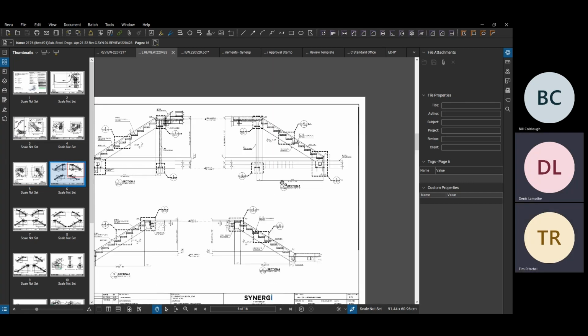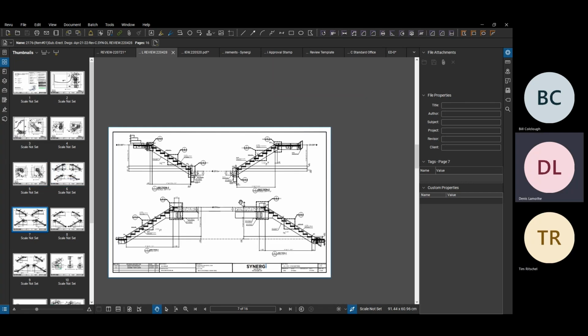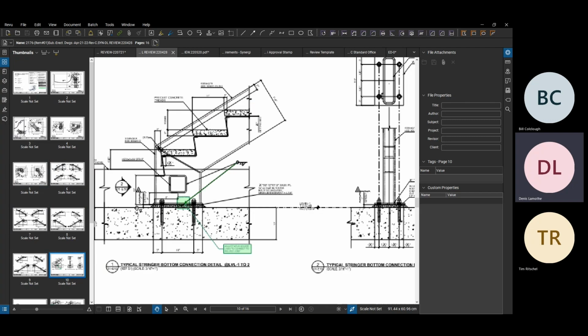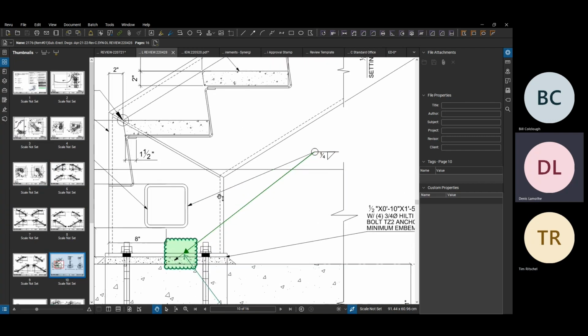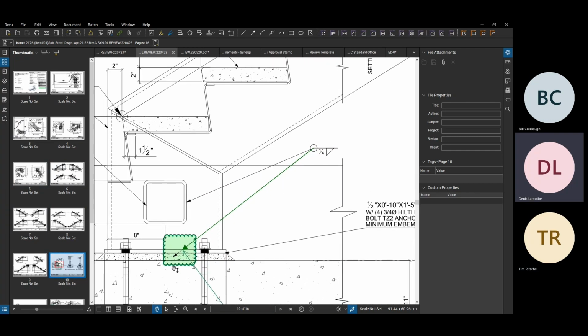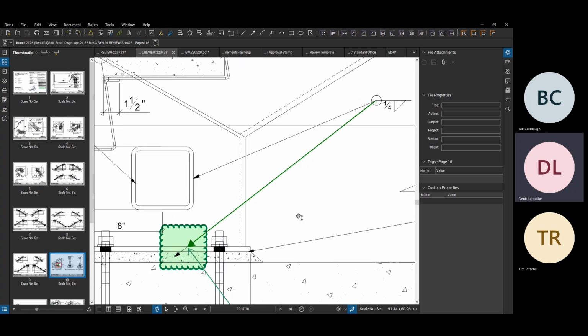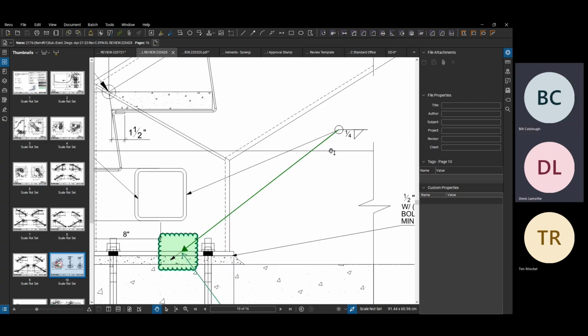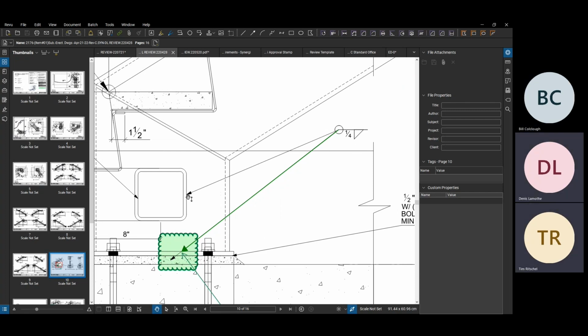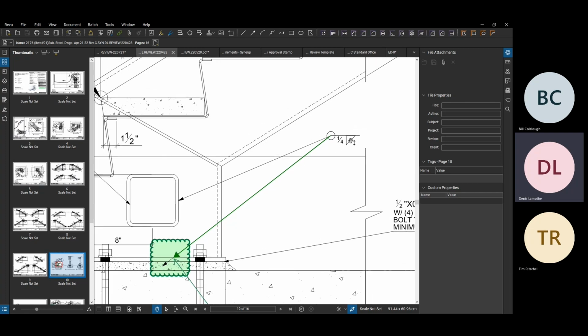We're going to check things like welded joint connections. Are the weld symbols properly added on? This one here was a weld leader that pointed to concrete, which is hard to weld. So, just little things like that. So it's pointing at the right object, at the right joint, the right size, the right type of weld we're displaying. And I'm pretty sure you guys know your welds, or the basic ones at least.